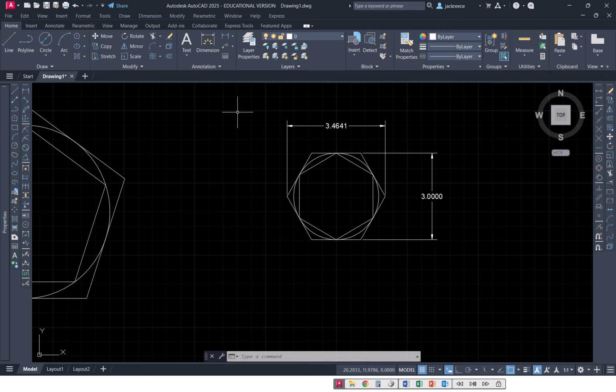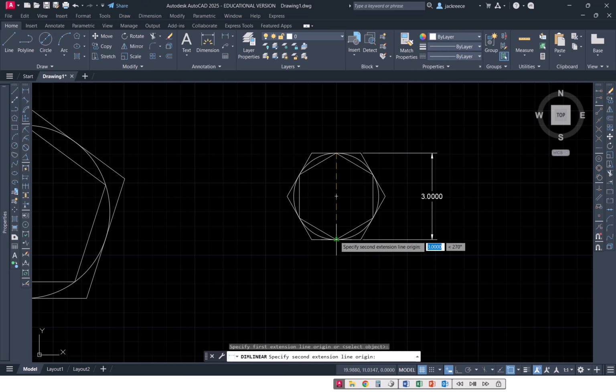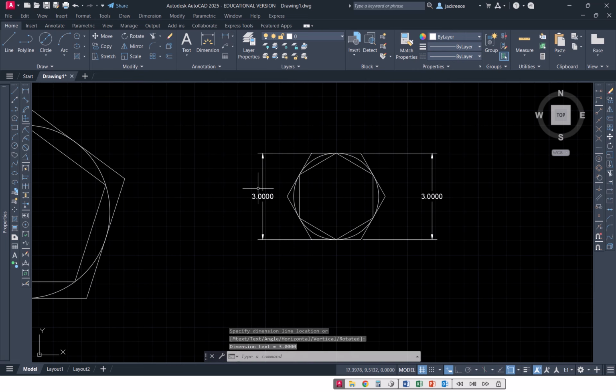And so depending upon how it's dimensioned, are you going to use inscribed or circumscribed? If it's dimensioned across the flats, like this one, then you use circumscribed. If it's dimensioned across the points, and maybe that's not a good example, let's do this one here. If it's dimensioned across the points, then you inscribe.